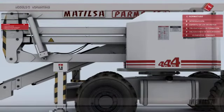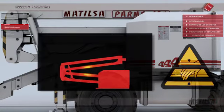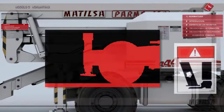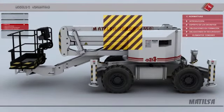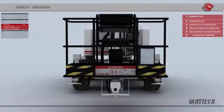Risks of falling and cutting. The platform should carry adhesive stickers that warn of the dangers of cutting, falling or crushing. Permanent danger warning signal. These are adhesive stickers on the machine, mainly on the sides of the moving parts. Rated load in basket. The access platform should have an adhesive sticker on the access to the basket in which it shows the maximum permitted load that may be elevated.